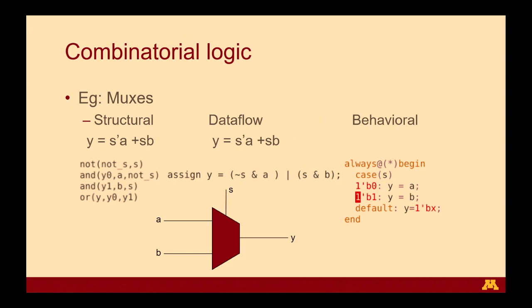So in this particular case, we can see that for a simple 2:1 mux, it just boils down to a case statement. And it need not be a case statement. You can even write this as, for example, an if-else statement. The only condition for a mux is that you need a completed design, as in all the ifs should be complete.